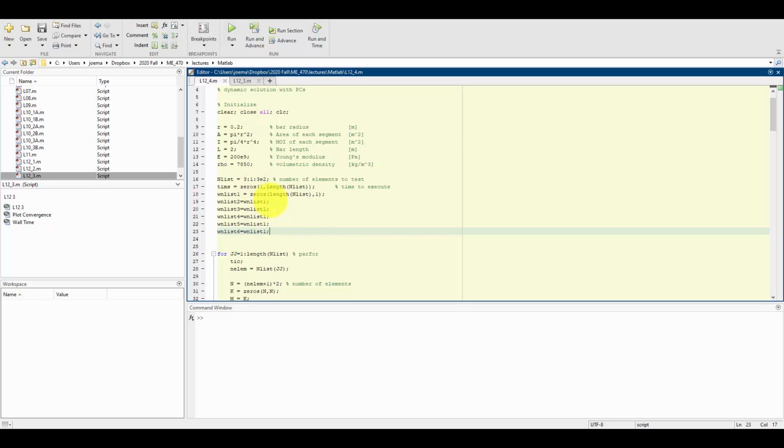And just so that I'm really going to be careful here, I'm going to track the first 6 natural frequencies as I increase the number of elements to make sure that I am going to have good quality results in the end. So most of the power, and if we looked at power spectral density, we would see this, that the first 6 natural frequencies are going to encompass most of the power in the fluctuations in the system.